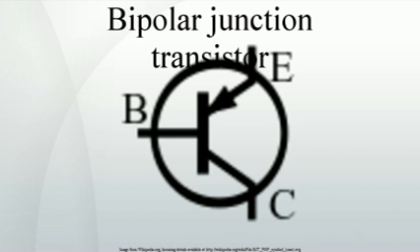V_T is the thermal voltage, approximately 26 millivolts at 300 kelvins, room temperature. I_E is the emitter current, I_C is the collector current, alpha is the common base forward short circuit current gain, 0.98 to 0.998, I_S is the reverse saturation current of the base-emitter diode, on the order of 10^-15 to 10^-12 amperes, V_BE is the base-emitter voltage, D_n is the diffusion constant for electrons in the P-type base, W is the base width. The forward and reverse parameters are as described previously.